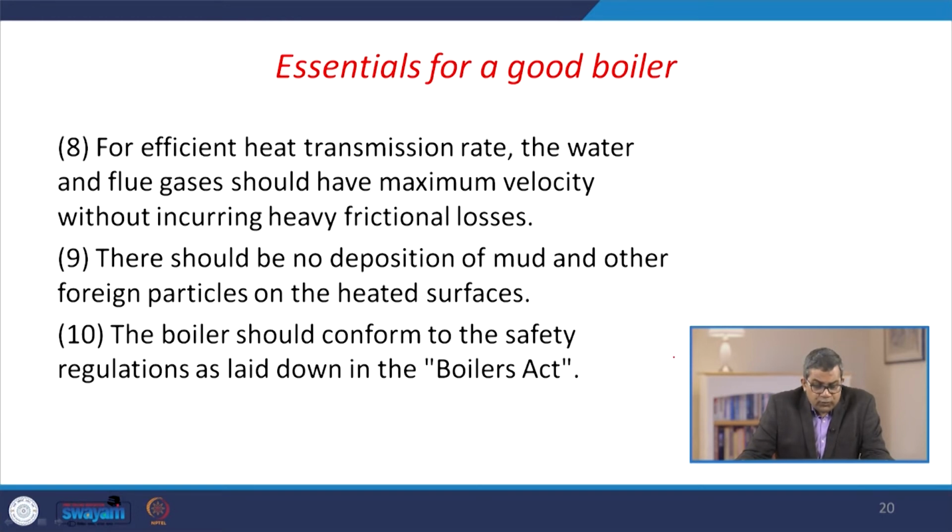For efficient heat transmission, the water and the flue gases should have maximum velocity without incurring heavy frictional losses, just to minimize the impact of scale formation within the tubes, etc. There should be no deposition of mud and other debris or foreign particles on the heated surface, otherwise the heat transfer may be badly affected.